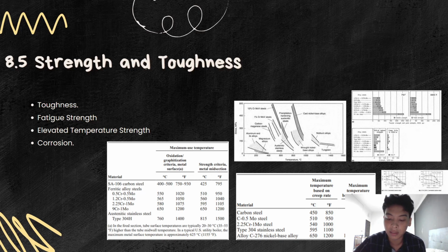The most effective and economical methods of improving fatigue strength involve designing the part to eliminate stress raisers, avoiding sharp surface tears or indentations that may result from punching, stamping, shearing, and even hardness testing, preventing the development of surface discontinuities or decarburization, or loss of carbon from the steel at a surface by reaction with the furnace atmosphere during processing or heat treatment, and improving surface finishes.